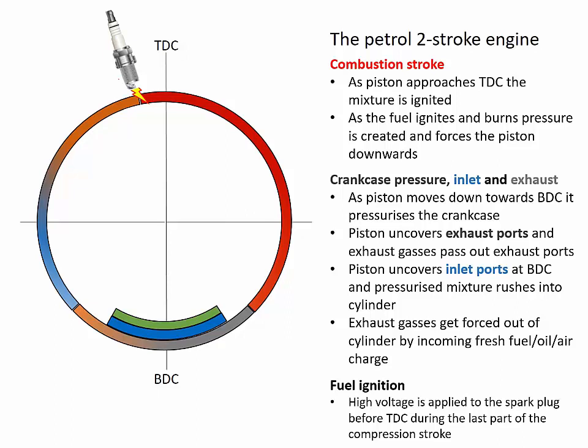As the piston moves down on its combustion stroke, it will uncover the exhaust port first, where the remainder of the combustion pressure will pass out the exhaust passage, and then as the piston moves further down, the transfer port will be opened, where it allows the fresh charge of air and fuel to be pushed into the cylinder combustion space, forcing out more exhaust gases.